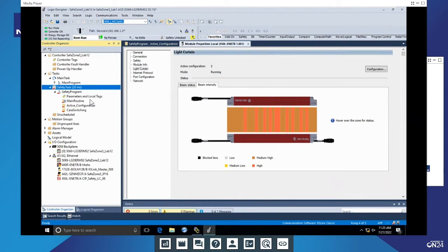This number is unique to each device. And if you replace, say for instance, your Ethernet block with a new Ethernet block, you need to reset ownership, which means you need to unlock your safety program, reset ownership, and then put the machine back into its working state. Yeah, the reason for this actually is so that you might have a CIP safety network with multiple different